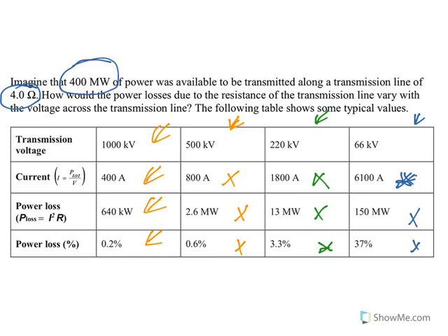All right, so this is where we want to be distributing our power, at those high voltages. So from the power stations into Melbourne or wherever it's going, they're high voltage, relatively low current, and so their power losses are lower, because we don't want power being used to heat up the transmission lines. We want it to be used to turn on our lights. Alright, so let's have a look at an example.